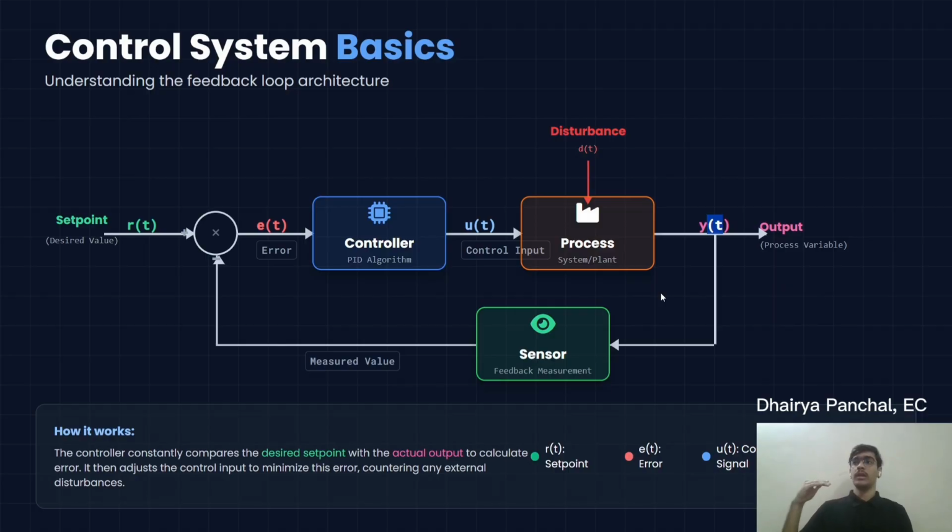The output would change with respect to your input, so there are no controls. You can only manually increase or decrease the input to keep your output stable, right? But when you have a feedback coming, it can be positive or negative. Feedback in this case, because we subtract something from our input, we call it a negative feedback system.